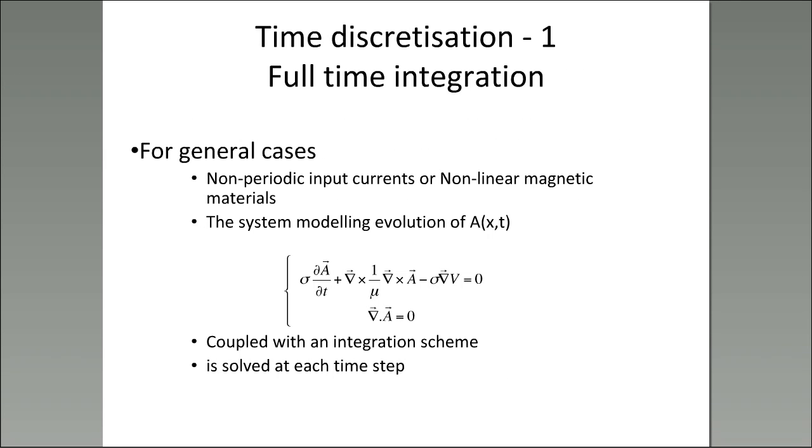So I have spoken now about space discretization. Now let us speak about time discretization. Here again, there are two different choices which you can have. The first choice, which is often used in modeling software, is the choice of full-time integration. Why? Because for general cases, when you have either non-periodic input currents or nonlinear magnetic materials,